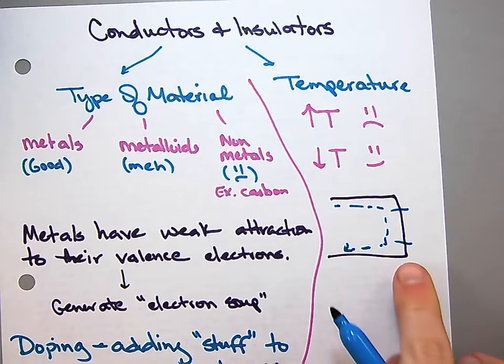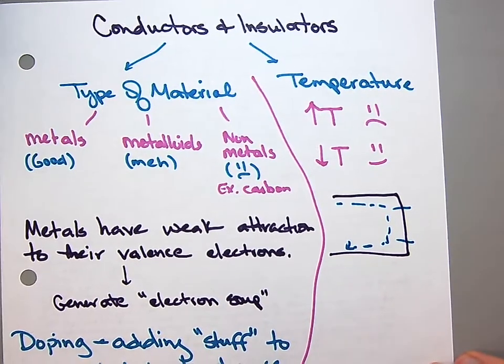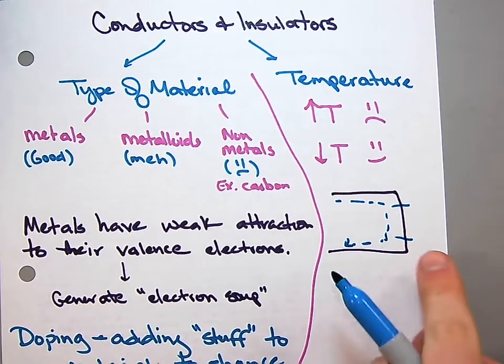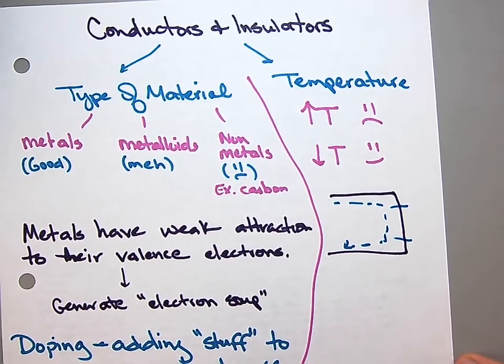Okay, so if the temperature is high, then what we're going to see is not much current goes through. And if the temperature is low, what I'm going to see is more current goes through. And all I got to do is figure out, okay, at 70, how much current goes through? At 75, how much current goes through? Map those, measure the current, and then I got a digital thermometer. Make sense? Okay.